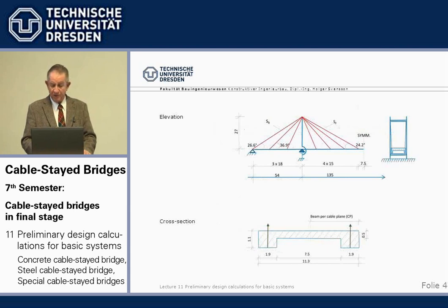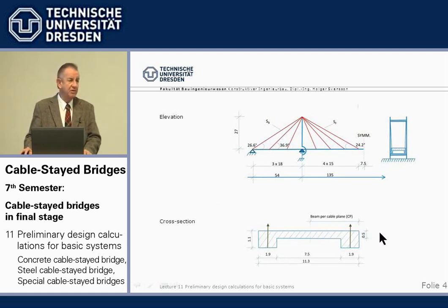And important for the calculations, if we consider cable-stayed bridges with 2 cable planes, as we normally do here, we calculate all the moments and cross-section properties for 1/2 bridge or per cable plane, CP.